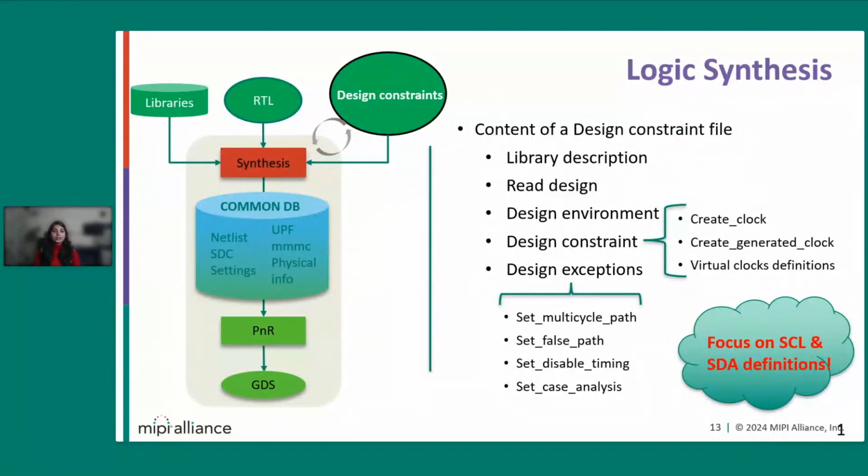Let's talk about logic synthesis. We know that logic synthesis translates the design RTL to logic gates in a given technology library. The design constraints are very critical and determine the implementation efficiency. So we know that badly written constraints will result in a poor implementation with a low figure of merit. So we need to carefully define the design constraint file that will cover all the functional constraints of the design.